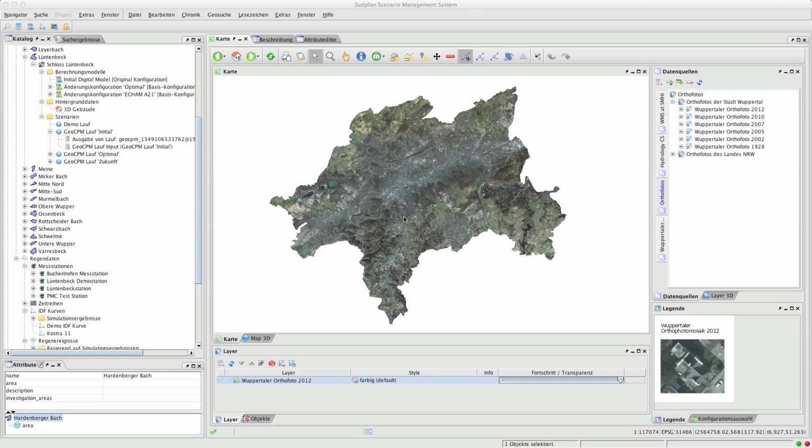At the example of the Lindenbeck Manor House, we will now play through a possible planning option to prevent damage by water. We will use the possibilities of the SMS to create two retention basins connected by a ditch so that water can be exchanged. Additionally, we add a wall at the back and front side of the manor house to prevent the water from slopping over the borders of the retention basins. Eventually, we will run this newly created configuration and we will see if we succeeded.